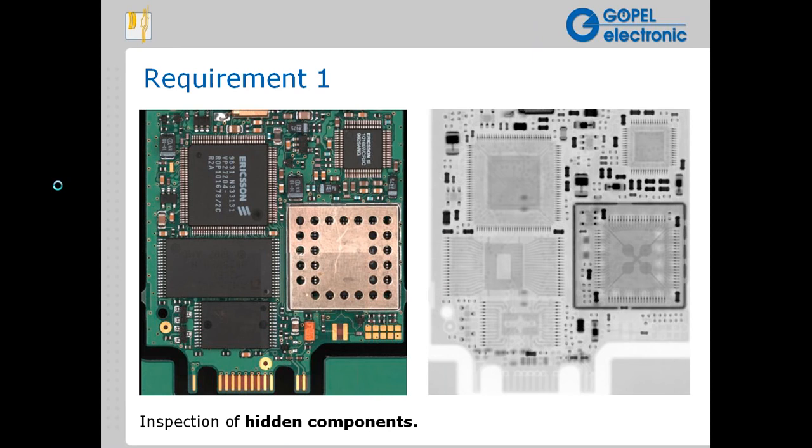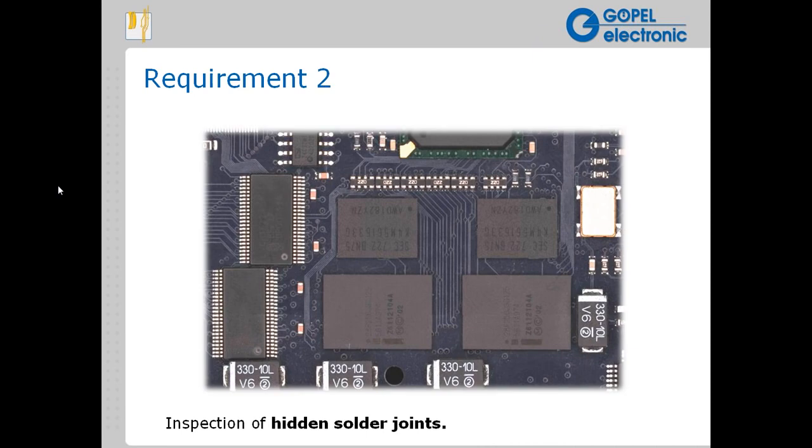But with X-ray imaging, we can in fact see the solder balls on the bottom of these devices. We can see details of the shape and density of the solder balls. In fact, if you look closely at the balls on the bottom devices, you can actually see voids in the solder balls there. So there's a great deal of detail here that we can see relative to these BGA devices. These devices would not be inspectable at all in any other case except for electrically testable. So X-ray gives you direct analysis and access to these solder joints.